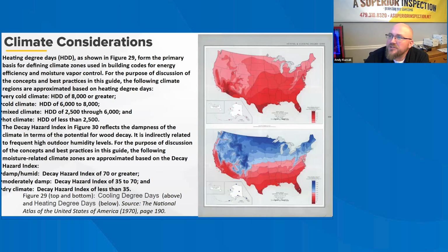In the northern US, moisture vapor problems are driven primarily by indoor relative humidity combined with low outdoor temperatures during the winter. In southern US, especially in the southeast, the problem is largely driven by high outdoor humidity and low indoor temperatures during summer months. Mixed climates are exposed to both conditions and can experience both types of problems. Therefore, many of the best practice recommendations in this section vary according to climate. The same is true of the underlying building code requirements.